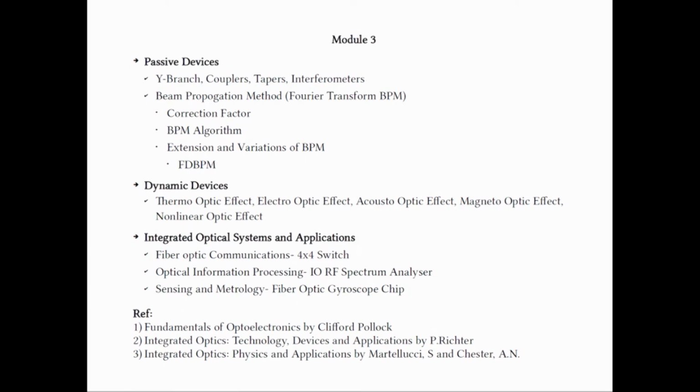So, there is a microwave coplanar strip line, a microwave waveguide on top in terms of the electrodes, and an optical wave in the waveguide. The propagation can be studied, and the electro-optic effect and all these effects result in refractive indices which are variable with propagation direction, and the similar techniques that we have mentioned in the previous chapter can be applied. The numerical methods can be used to study these properties.